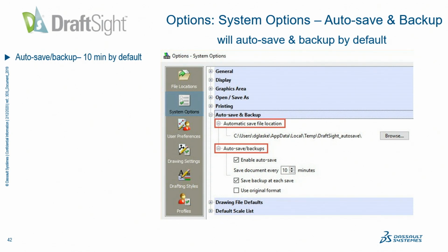And if you have templates already in AutoCAD, you can just bring them in and point to them in the locations where they are. You don't need to redo that stuff. So if you have any default templates that you already have from AutoCAD, we can just bring them in. Where we would bring them in here, I don't remember if I have it on the slide, but we would just point to profiles and point to those templates where they are, so it knows where to go look for them. Because DraftSight will load with its own default templates, so either change the location or put them in that location if you want.